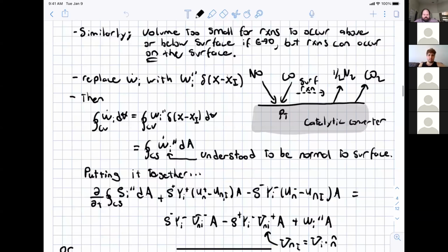And I'm going to break momentum into the normal, which is again pointing up, and the tangential direction separately. And so the conservation law for a particle is the time rate change of momentum in the normal direction is equal to the sum of the normal forces. So here I have a control volume, and I'm keeping track of all the fluxes of normal momentum going up through the top and in through the bottom. And also we do need to account for the fact that if the interface is moving, we are defining our control volume to basically move with the interface. And remember, we are shrinking the height of this control volume to be nearly zero, such that the total cross-sectional area on these sides is negligible.